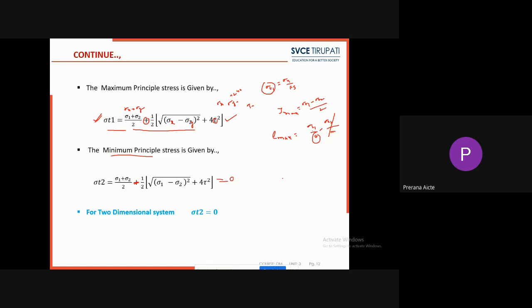So all of you just remember each and every theory, what its other name is, and which type of material each theory of failure is applicable for. First one, what is it, rectangular; second one, maximum shear stress, hexagon; what is the maximum principal strain? Parallelogram. What is the maximum distortion? Ellipse. What is the maximum strain energy? Also ellipse.